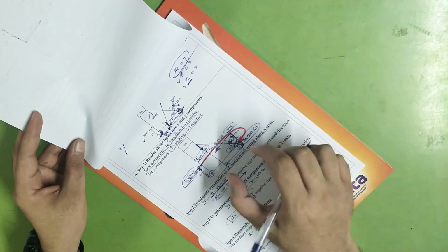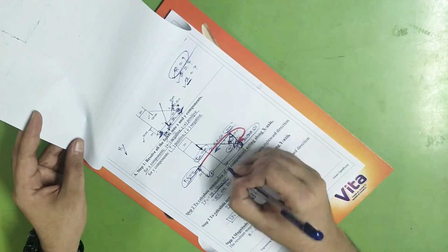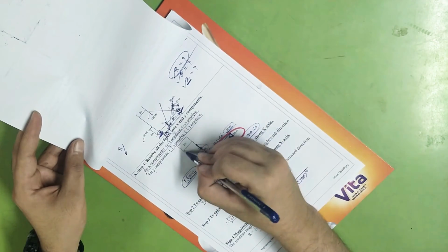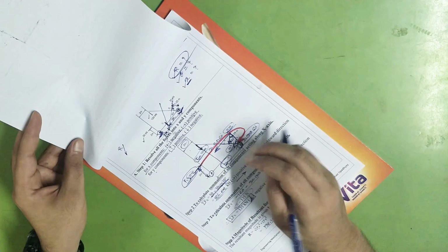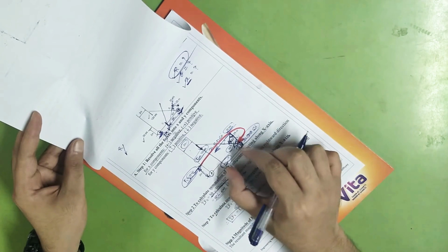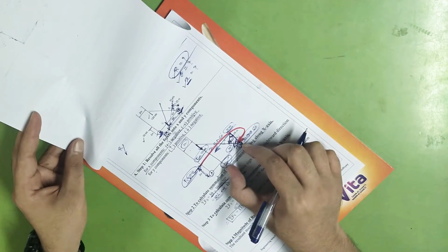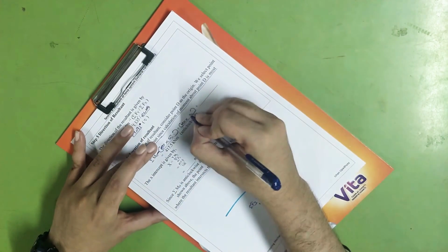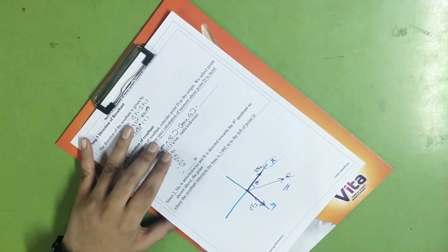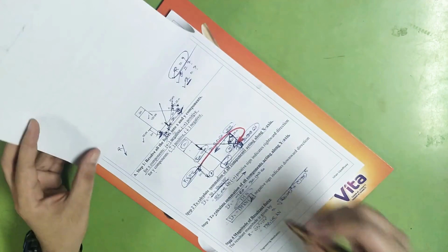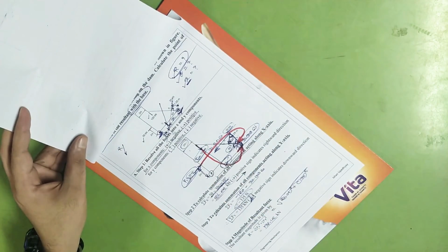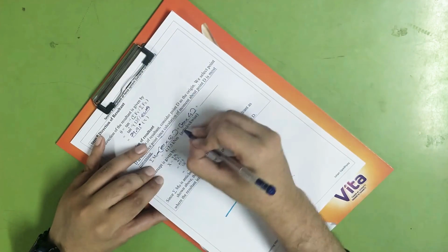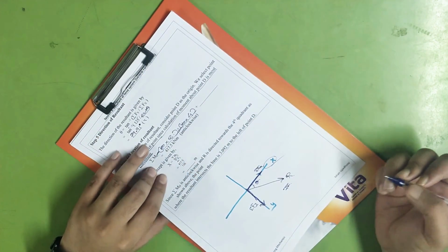Okay, now the total distance is given to me as 6 meters and the remaining distance is 2 meters. Then what will be this distance? That will be 6 minus 2, which gives me the required distance, and that is how much? 4 meters. So here I write 120 into 4. Next we will have to check its direction. Here you can see that this will create moment in anti-clockwise direction, so for that we put a positive sign.